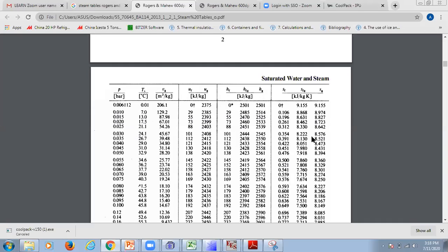Not only one time; you may be repeating this test several times and get the average values for the particular temperatures and specific volumes. Repeat the test at the same pressures, closed system, constant pressure heat addition.